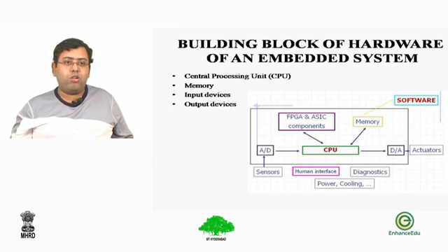It has to talk to the real world, for which there are AD, analog to digital converters, and digital to analog converters. The analog to digital converters accept inputs from the sensors or transducers and perform a conversion of the analog signal to the digital signal, which the CPU can compute on. The CPU again produces the digital signal, which has to be converted into the analog form before it can be used for actuation purposes, which makes sense to the end user.